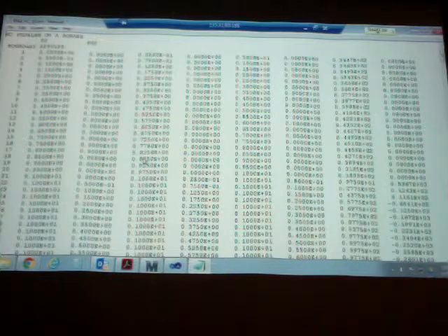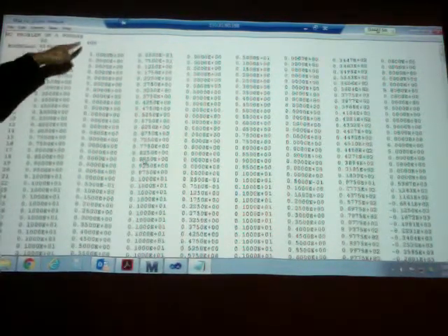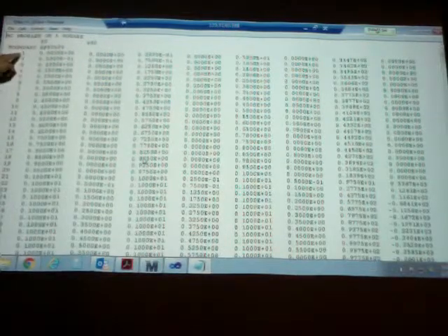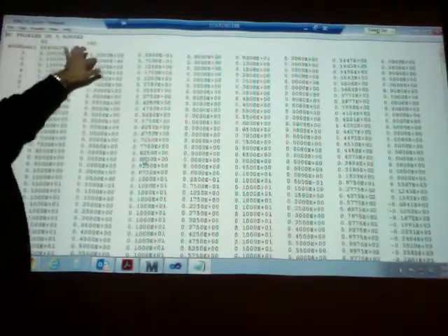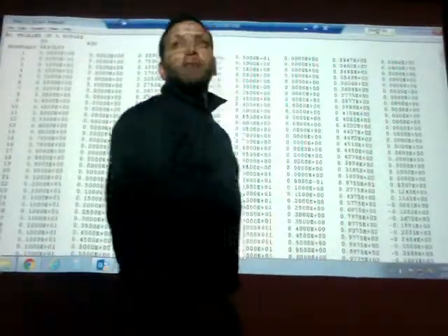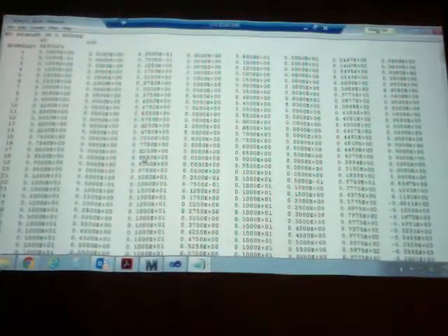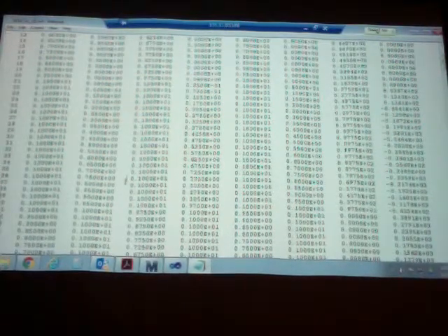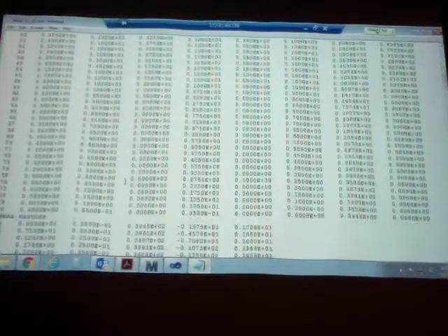I produced a file called output. It has information about the problem: the title, number of boundary elements, number of internal points. It has the location of all the boundary elements, x, y for the 3 nodes, the temperature and the flux. And then after 80 lines, for this particular case, it has the internal results.